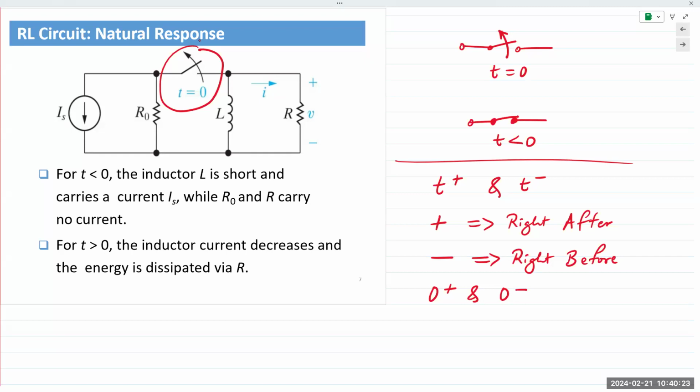All right. So the next question being asked was actually going to be my next point. Why is there no current through the resistors? This example assumes that the switch has been closed for a very long time. So if you read the words a very long time, it indicates that the system was already at steady state.